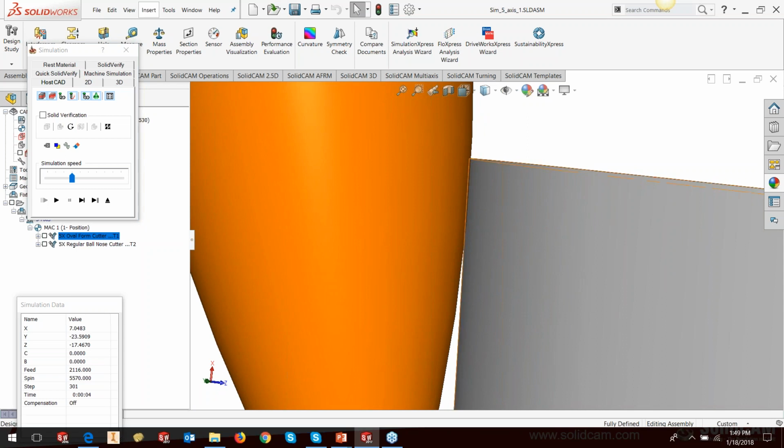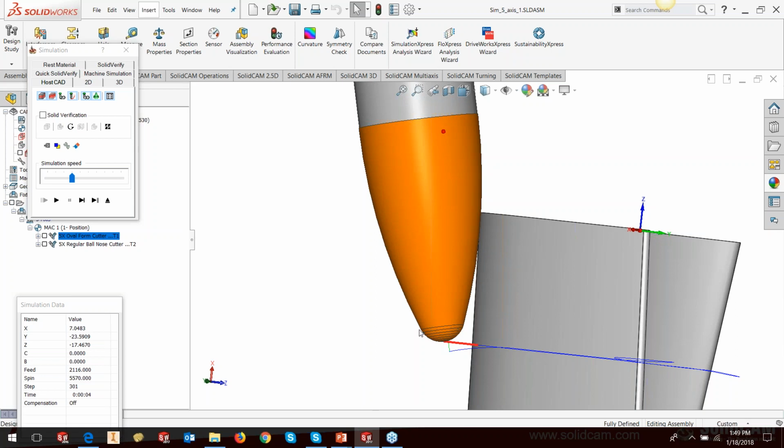This big flank having a radius of 90 millimeter or 100 millimeter is in contact. That's the cutting area and not the tip, because the moment the tip comes into play, our side step drops dramatically. Because of this large flank radius, I can give a much bigger downstep, yet achieve the same kind of finish that I would achieve using a ball nose with a much smaller step down.